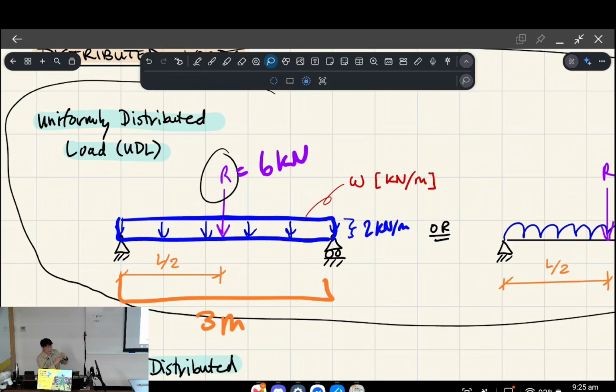So on the y-axis, you're thinking of w, the distributed load. And then the base, or the width of that rectangle, is the length that the load acts over. Okay. The other thing to note is the center of shape. The center of this rectangular shape is in the middle, right? So at L/2 is where the equivalent point force would act.